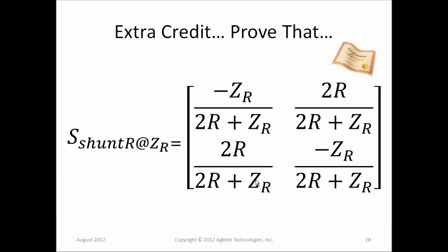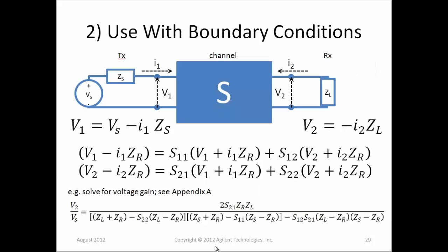Notice that with S parameters, the equations always involve this reference impedance. You have to specify a reference impedance with S parameters. It's part of the specification. You can't just specify the matrix elements. You also have to specify the reference impedance that the S parameters are referred to.